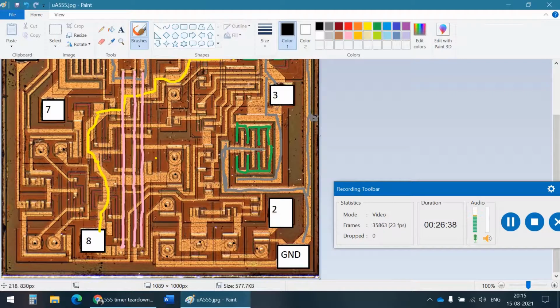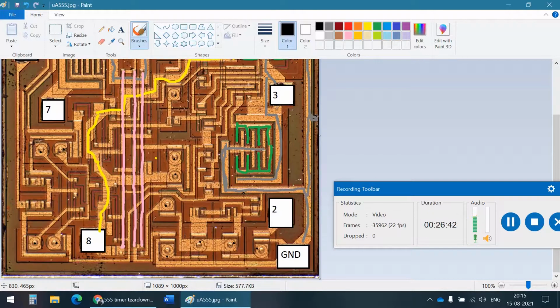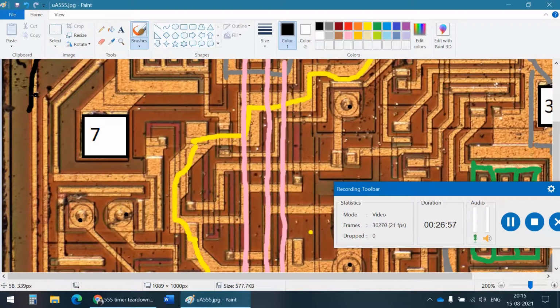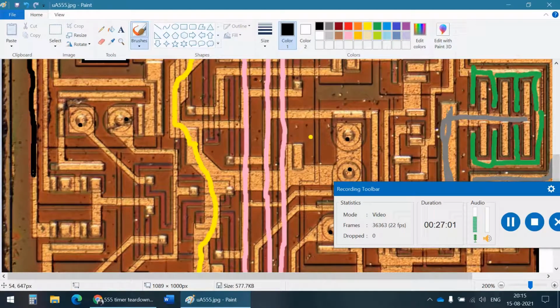Now if we go here, we've identified the four. Let's look at one of the pins. The pins are easier to get across from. So this is pin 2. Let's see, why not, let's go with pin 6. Okay, pin 6 seems to be isolated. It seems to be only connected down this line, down on here, and seems to be connected here. And you can see there's a break here. So this, I would say, is a transistor, and then there's one more transistor connected.